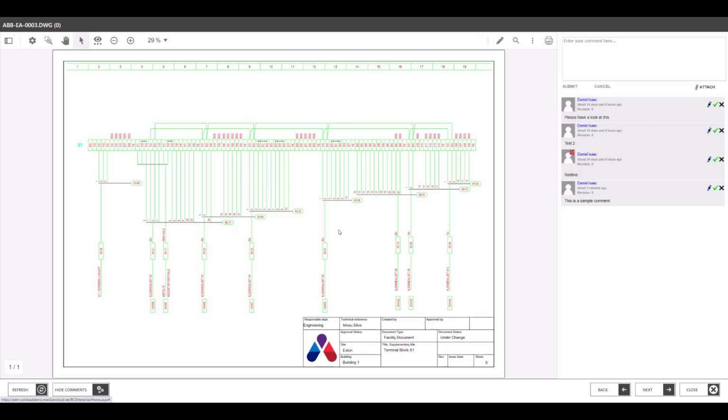There are several ways of doing this. You can have redlining tools to draw over this PDF rendition, or you can have text comments on the side here. So let's expand the redlining tools by going into edit mode. That opens up a host of different options that are available to you to create different markings and shapes, as well as adding freeform text.